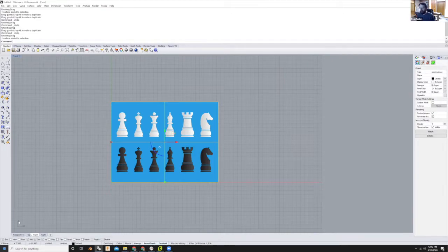So O-snap on. And what this means is anything I draw will predictively snap to an endpoint if I'm close to one. I don't use near or point too often, so I keep those deselected. Midpoint, center, intersection, perpendicular, tangent, quadrant, and knot and vertex. I will use them periodically, like if I'm working with circles, maybe I'll turn quad on or tangent on if I need a line tangent to a circle.